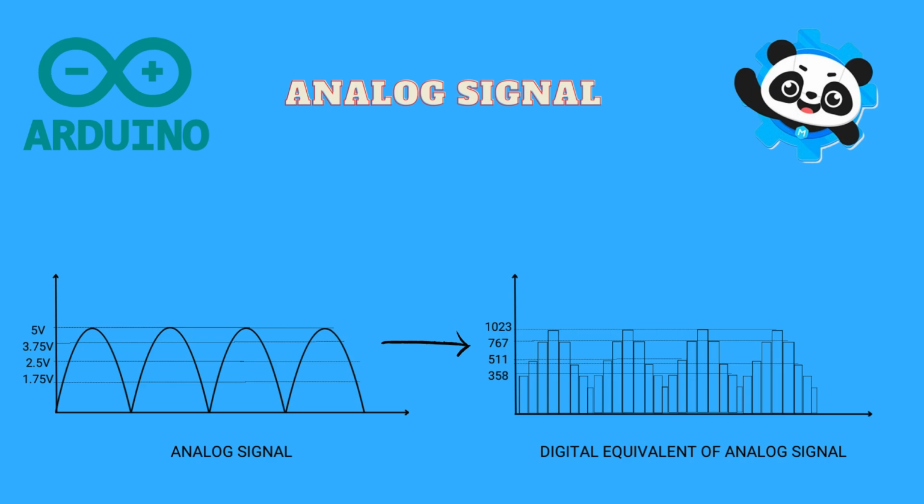Let's explain with a simple example. Within an Arduino with a measurement range of 0 to 5 volts, 5 volts corresponds to the number 1023. Using this ratio, for instance, a voltage of 3.25 volts corresponds to the value 665. When using analog signals in our programming processes, we must pay attention to this ratio and proportion.